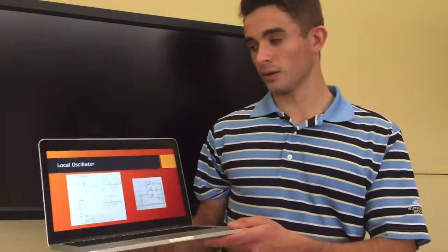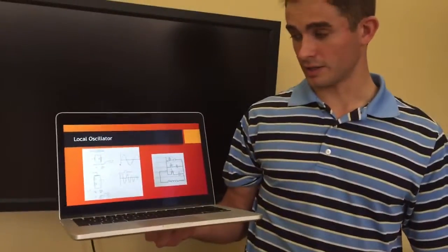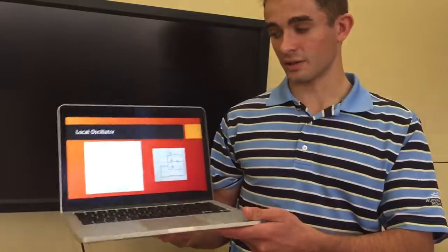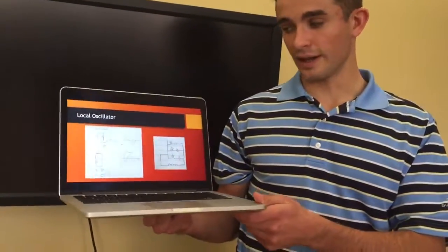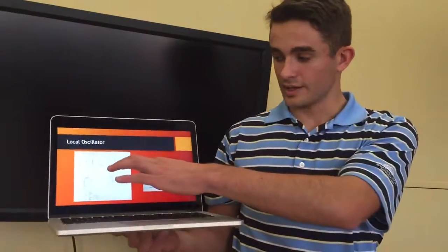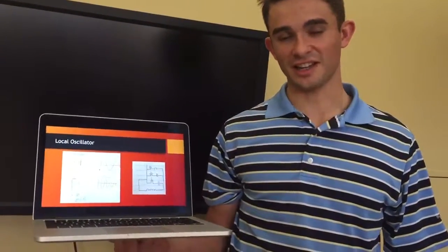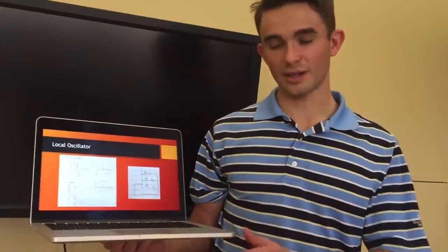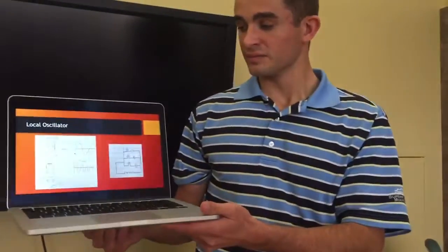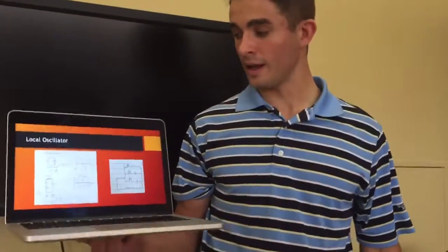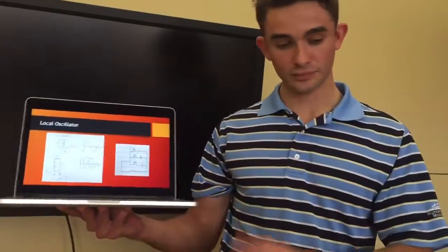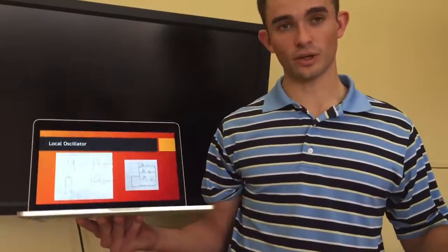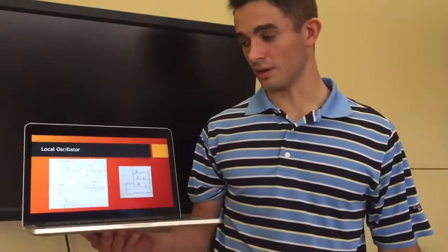All right, so how a local oscillator actually works on a circuitry level is we can build a simple one as an LC circuit. Ideally, an LC circuit has an omega naught, our resonant frequency, at 1 over the square root of LC, and it'll create something like this. But there's no such thing as an ideal LC filter or local oscillator. So there's some attenuation, as we can see right here, and this attenuation causes the signal to go to zero after a while. So we have a transistor tank that fills this quote-unquote LC tank every time it starts to run low.